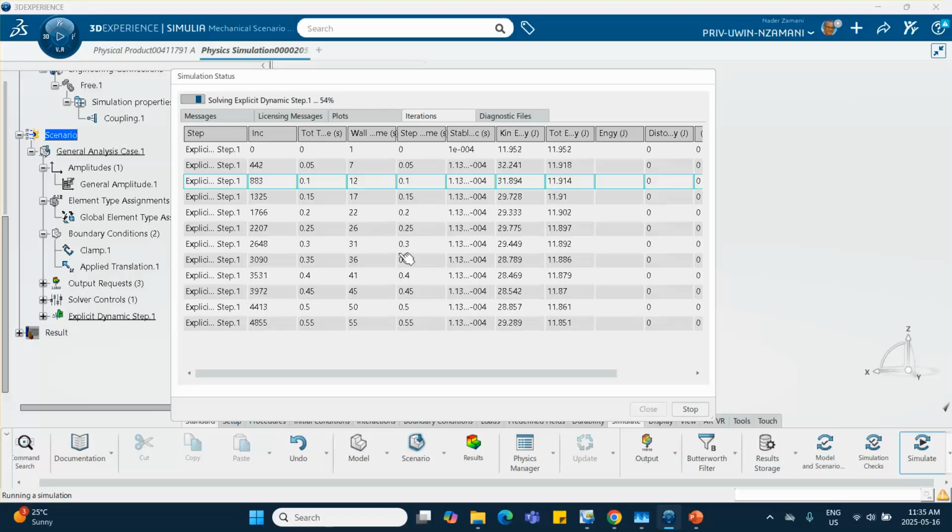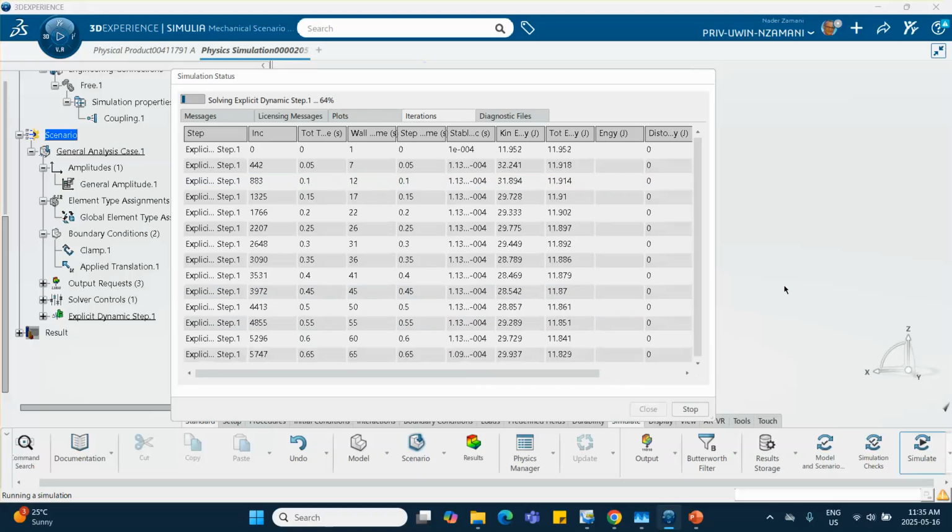If you wanted to do that, there is a box here. It says output. Click on it, create an output request, and ask for whatever you want. Because there are some preset and default information is going to spit out. If you want more than that, you have to go ask for it. This is almost done.